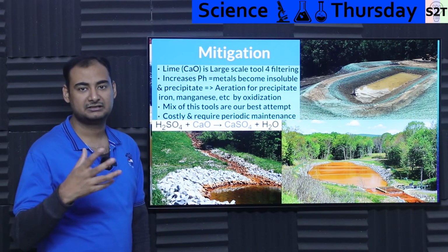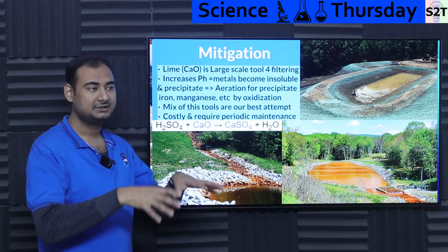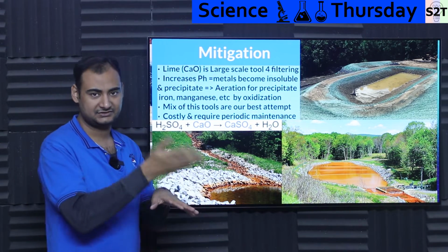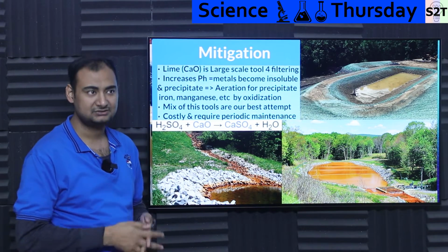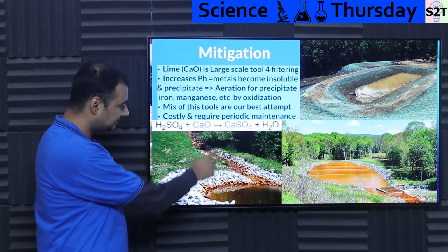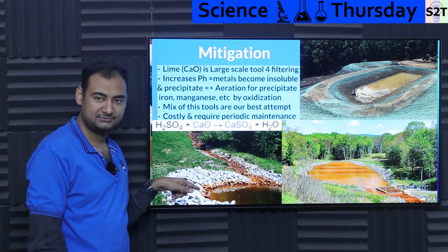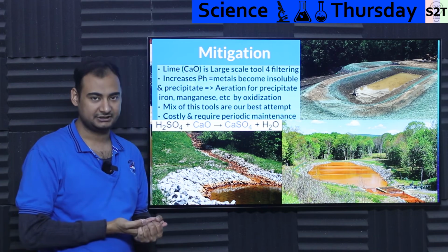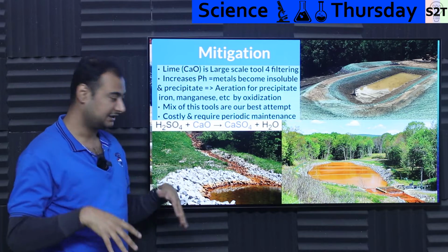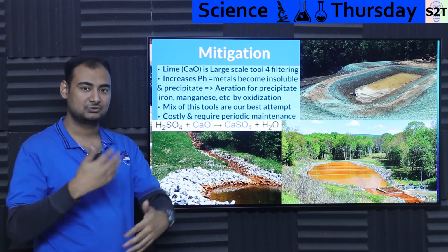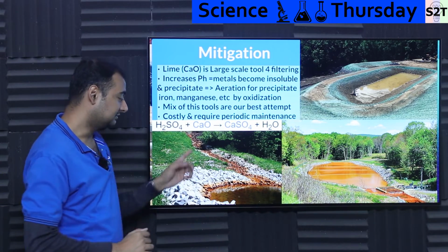That simply means, let's say you are in a drier state, and because generally you are digging deep, there is a very good chance you have a water reservoir that is draining into it. You're going to pump it out, okay, but it's not a lot of water, and you do not have too much rain, so it's not going to be a bonkers amount of water. So people can do this. Basically, they're going to make a wandering path. That path will be covered with limestone, and that lime will sort it out. Basically, lime will increase the pH, and then the iron and all that will oxidize, and because it's rocky, it has so many aeration sites, the iron basically creates a formation layer. Now this is awesome.